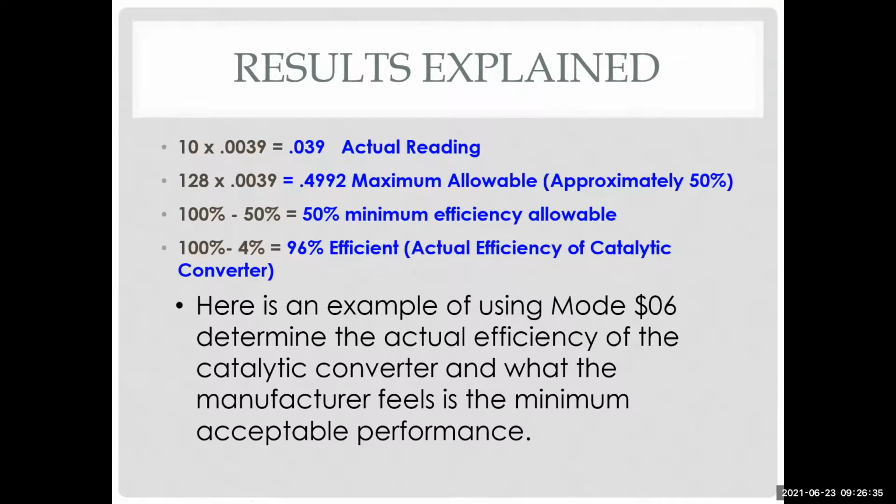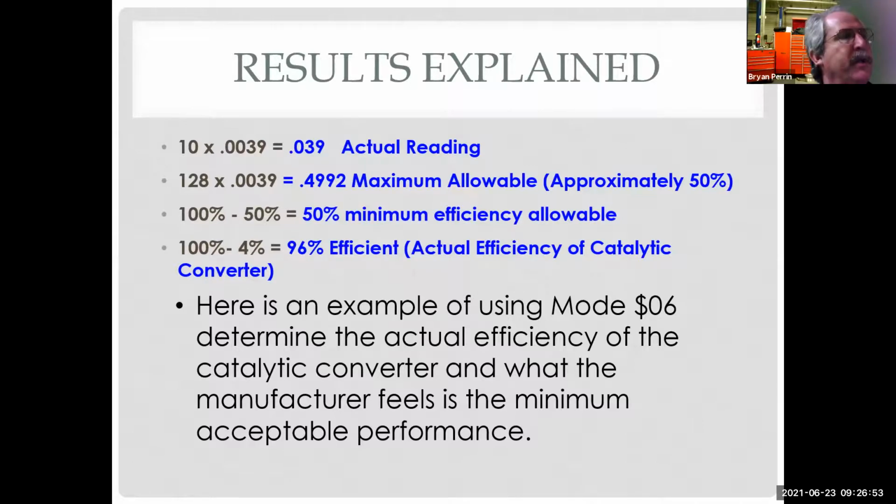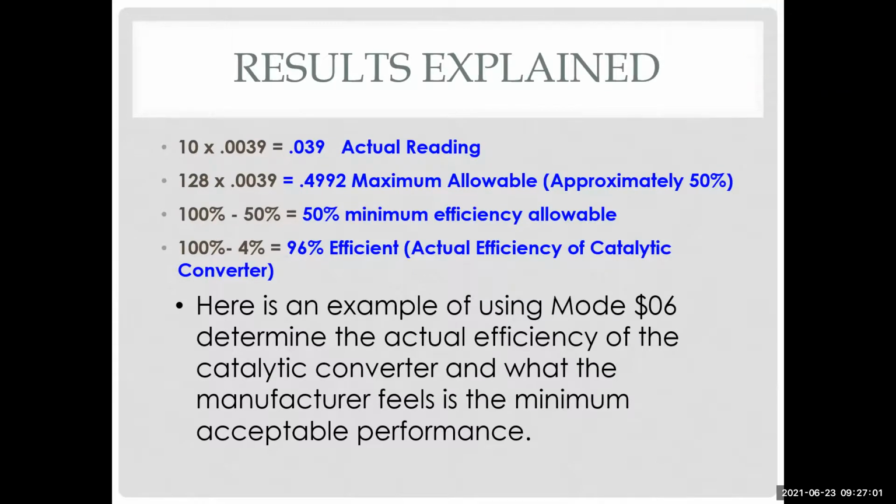Hey, Brian. Yes, this is the test that has a maximum allowable. The other previous test only has a minimum, and they both pass. So that means the two results are higher than the minimum allowable. Right. So in this case, because we're measuring the amount that it degrades, if my result is above my maximum, we're saying it degraded more than it's allowed.